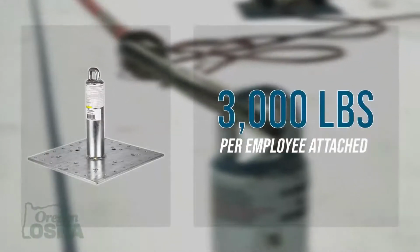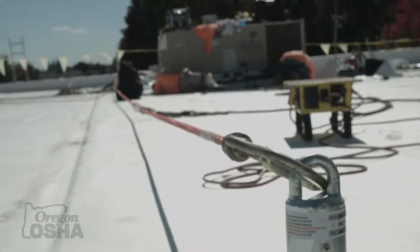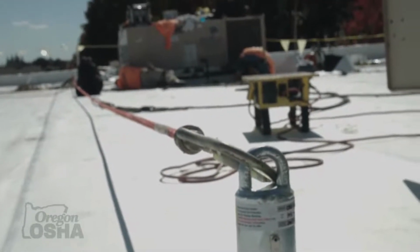Anchors used with fall restraint need to be able to support 3,000 pounds per employee attached. If your anchorage is less than 3,000 pounds, a qualified person needs to design and install the anchor, determine if it has a safety factor of 2, and supervise the work being done.